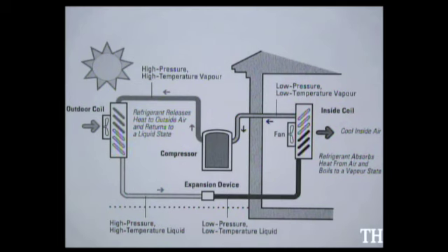But now, because the evaporator coil is working outdoors, there's a chance for it to ice up. Therefore, the system must go through a defrost cycle. To make the system defrost, the unit has the refrigerant flow just as it did in the cooling, so the reversing valve changes positions. Now you're in the AC mode.